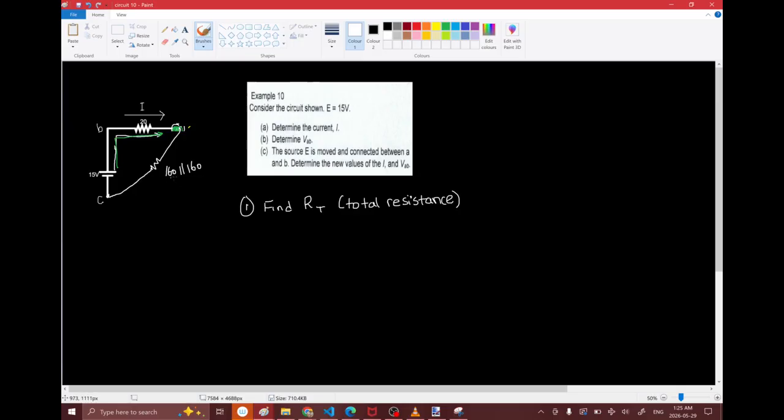And whenever you have two resistors that have the same value and they're in parallel with each other, the resulting resistor will always have half the value of the original. So I don't even need to do any math here. Oops. Or maybe I should have. 80 ohms resistor. There we go. So 160 in parallel with 160 is equal to 80.